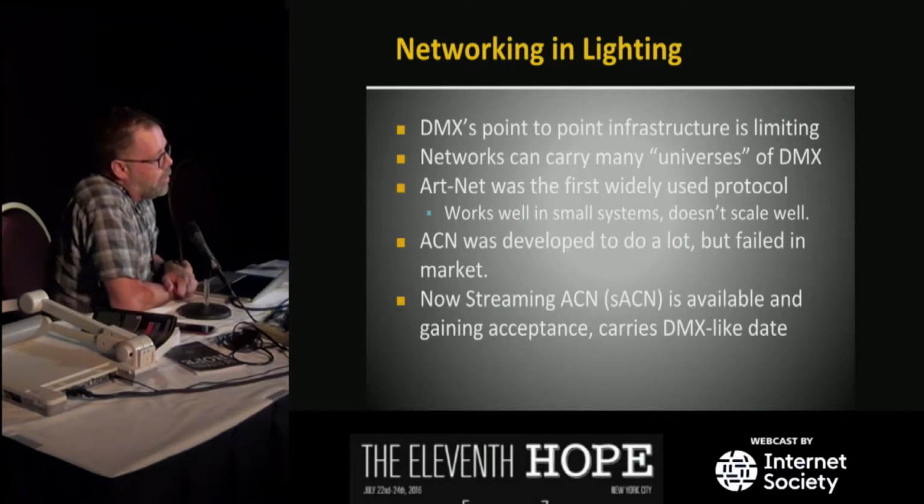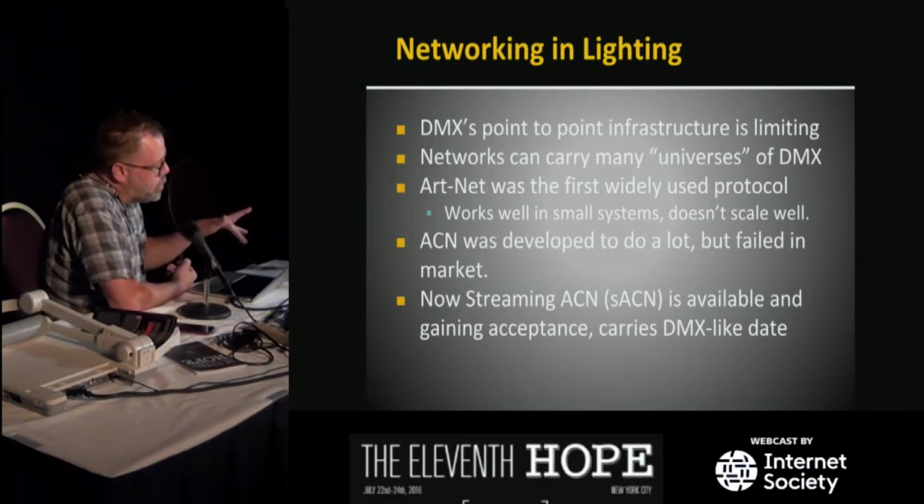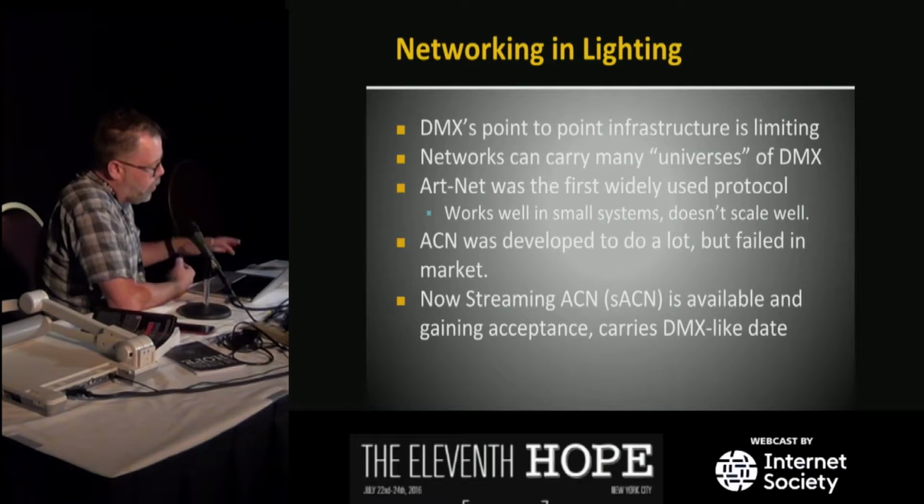So that's now our alternative to ArtNet, and that one is a very modern network-focused protocol that deals with all the issues, multicast, all these other things that we have issues with in modern networks, are all covered by that. So those two, streaming ACN and ArtNet, are the two most widely used lighting control protocols in the market right now for networks. I would prefer streaming ACN myself, but they'll both work.